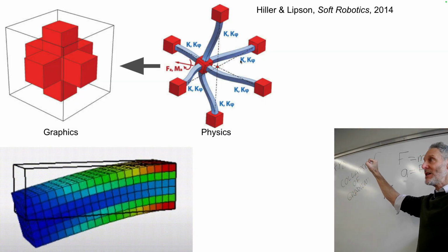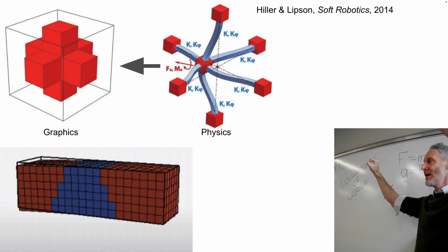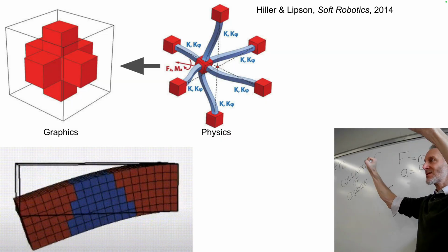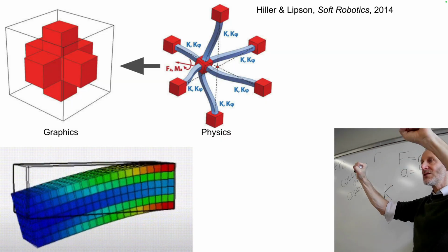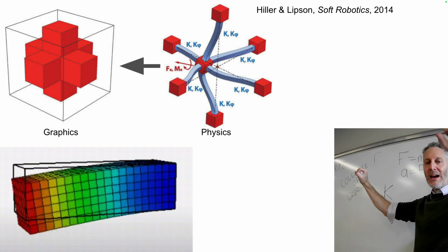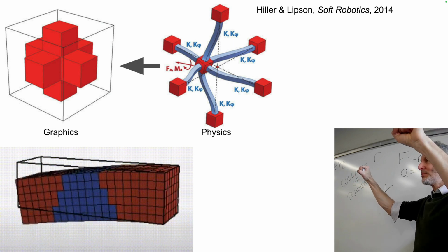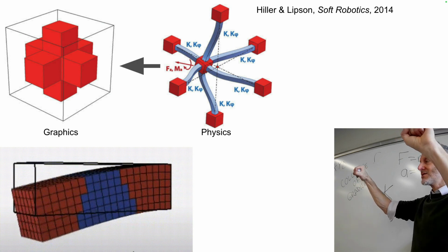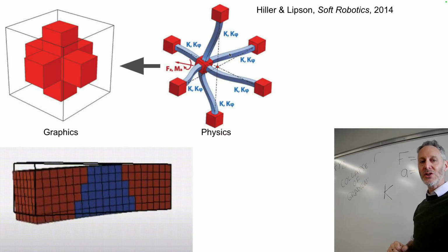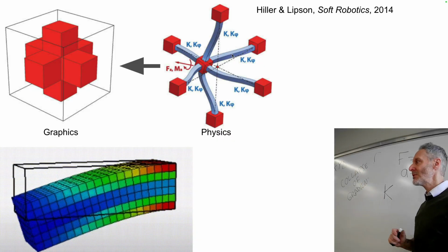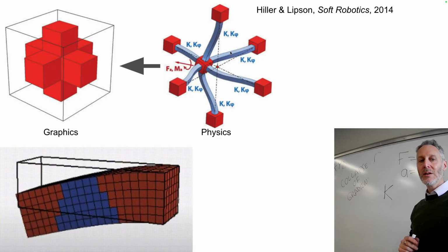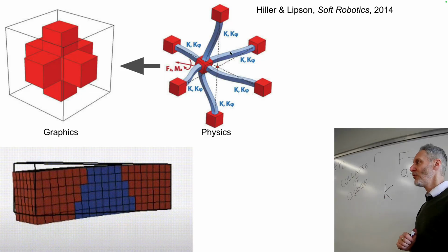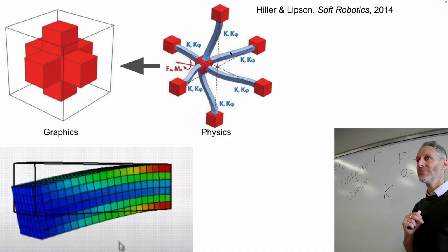If we think about the beam now as being connected at 2 ends, there can be forces that push in the x direction, push in the y direction, and the z direction. And then 2 of them that twist the beam in the 3 different directions. They're trying to induce yaw, pitch, and roll in the beam. So we've got 6 numbers associated with each beam that connects pairs of voxels together.